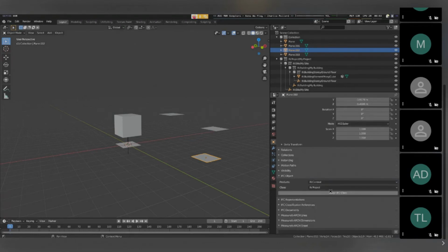Finally, there's context as well. Right now, there's only 2 to choose from. There are 2 types. The most common one is a project, and a project will cover the majority of the cases, which is when you're actually building a building. A project library is essentially a kit of parts or preset wall library or window library that you can reuse again and again. It's basically like an asset library or component library. There's various terminology.